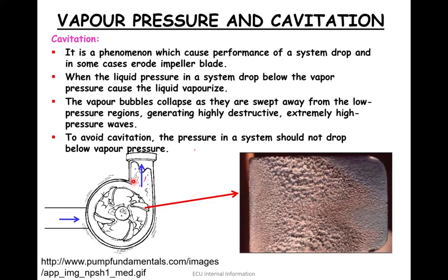Bursting of the bubbles forms a stream of liquid, which acts like a jet of flow. In that case it damages the propeller, and this is where what is called cavitation happens.